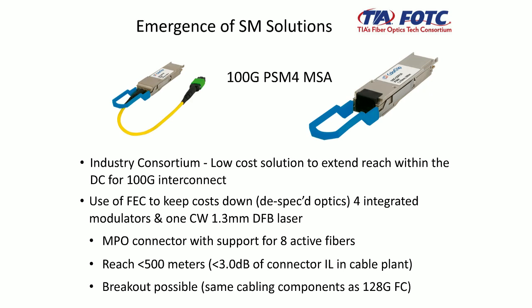even for that data center example that I showed, the Langfang data center, this would cover a lot of ground. The downside of this is traditional single mode transceivers that support 10 kilometers, very highly spec'd, might have 5-6 dB of budget. Well, when you start to de-spec these things, in this example here you've got 3 dB now instead of 5 or 6 dB. So that allows you a certain length and a certain amount of connector loss in the channel.